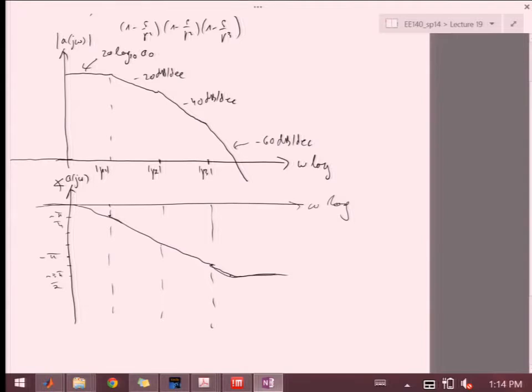And then we looked at the point where the sign of the gain changes. And we're saying that's a critical point. The frequency we'll label omega 180, because at that frequency the gain flips. So the phase is 180 degrees, so the sign of your A0 flips.